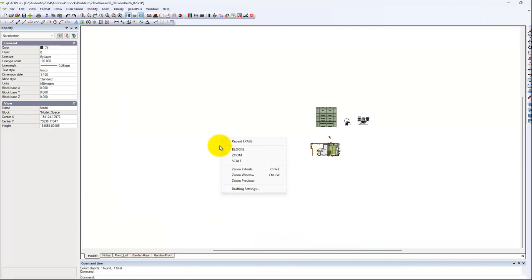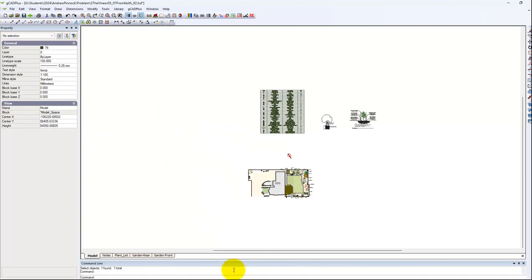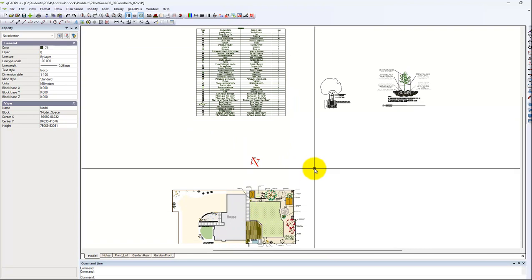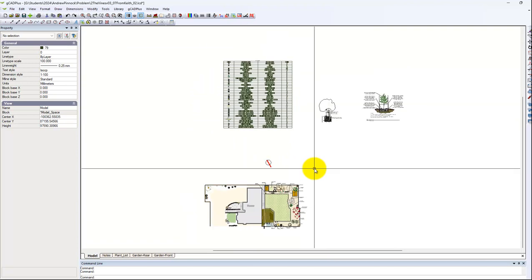And now if we try zoom extents, regen, zoom extents, we appear to have got there because we're jammed at the top and bottom. So we've removed some errant text, and that's outside the scope of this drawing, but it confirms that our designer has brought symbols in from sources that we have no control over and just incorporated those into the drawing. And I'm not sure that is a wise approach. So zoom extents, well worth coming to terms with.